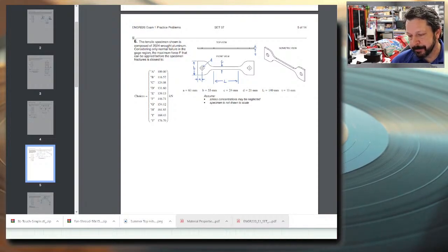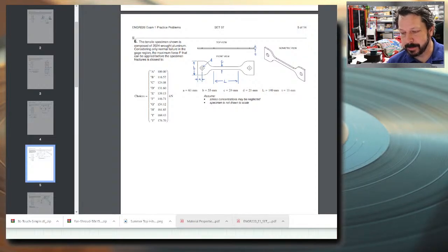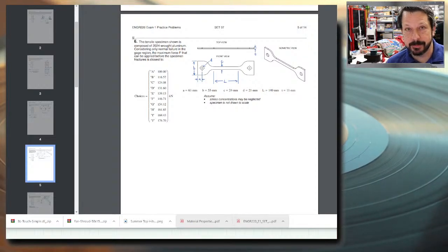With pulleys, is the tension in the cable the same throughout the cable always? In our course, yes. In other courses, no. If you said it with frictionless pulleys, is the tension in the cable throughout the cable always the same? Then yes, if the pulley is frictionless, which is the case in our course, the pulleys are frictionless. In the follow-on courses, the pulleys are not frictionless, and then the tension on one side of the pulley is not the same as the tension on the other side.